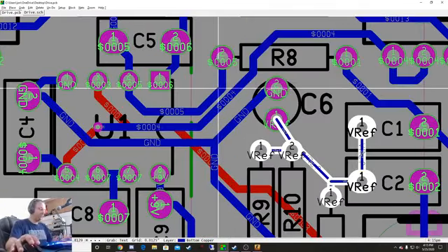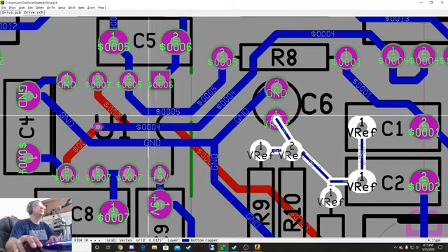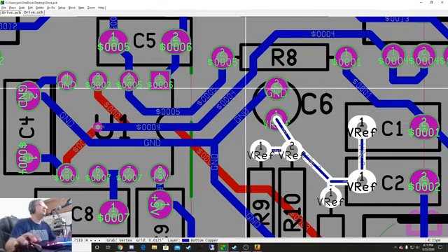And the other things I would do is I would start creating more space between stuff. So these spacings are fine, but the more space you have, the more room for error. If you have etching errors, then having more space means that etching error isn't going to cause your prototype not to work or your production board not to work.